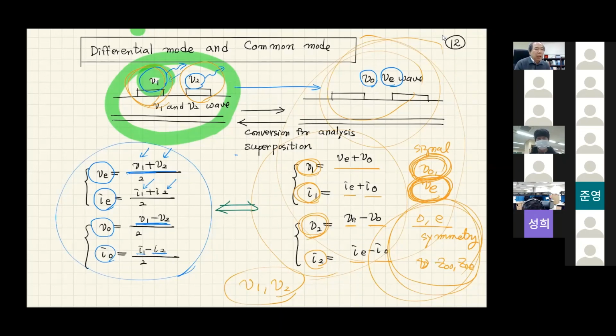Why do we, in PCI Express, HDMI, USB, and Serial ATA, use a differential scheme? Because to send really high-speed signaling and reduce the EMI, we really need the virtual ground plane. Without a virtual ground plane, we will never be able to send high-speed digital signals from one end to the other. So that's why we are spending time here.